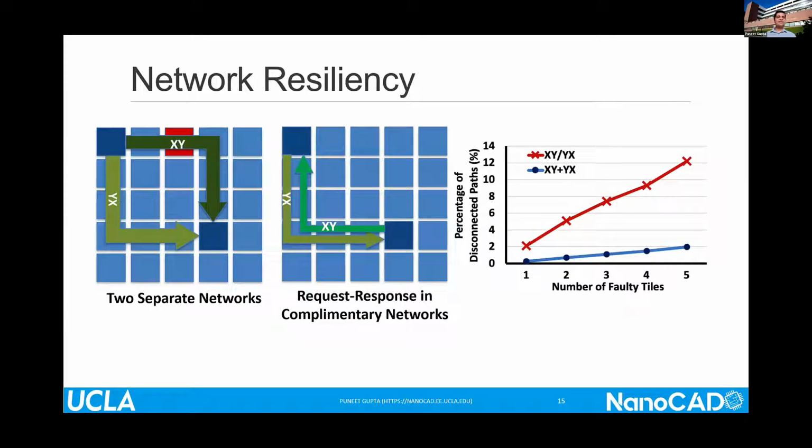That basically means the clock should be able to go everywhere, power should be able to go everywhere, and in the network, we should be able to go everywhere if a certain network node essentially stops working. Here, what we did was use simple network resiliency tricks. We do dimension order routing, but have 2 parallel networks between the same connections.